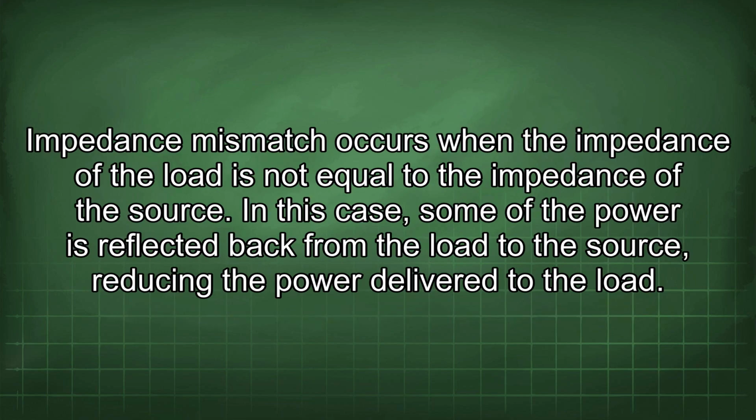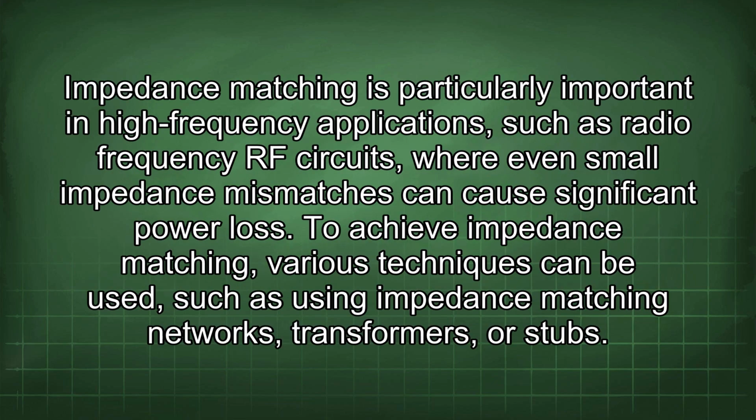Impedance mismatch occurs when the impedance of the load is not equal to the impedance of the source. In this case, some of the power is reflected back from the load to the source, reducing the power delivered to the load. Impedance matching is particularly important in high-frequency applications such as radio frequency RF circuits, where even small impedance mismatches can cause significant power loss.